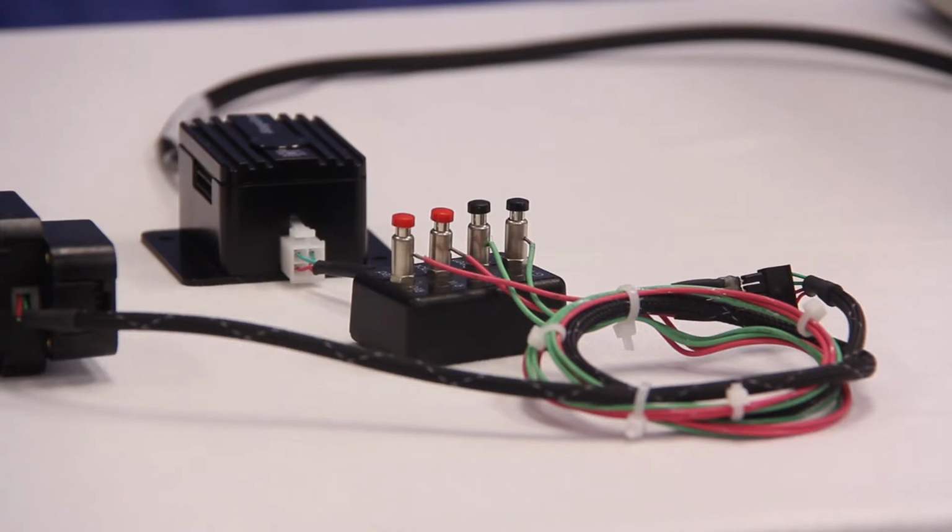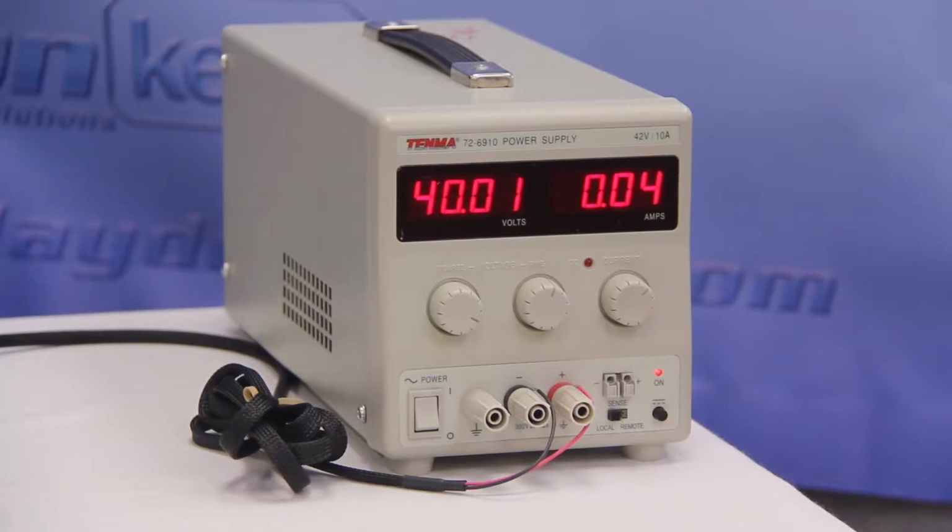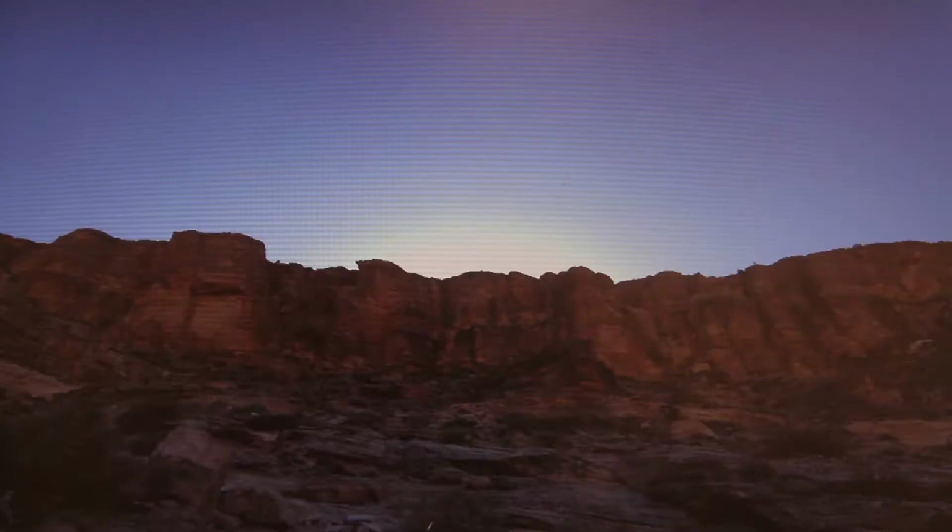Here we have a PCM4826E drive utilizing a USB communication along with a NEMA size 17 motor mounted on one of our BGS rails. Since we are using a motor with a 5-volt winding, the drive will be powered with a 40-volt DC power supply to maintain an 8-to-1 voltage ratio between the supply and the motor. On program startup, the user will see the following screen.